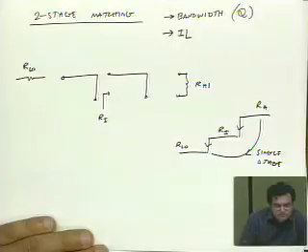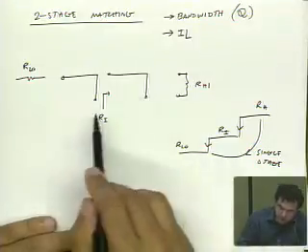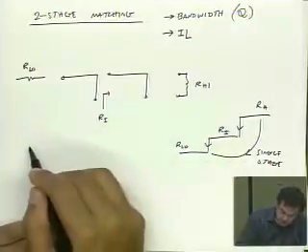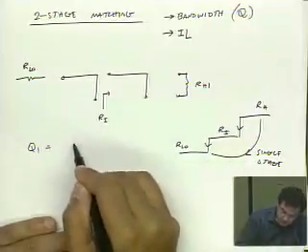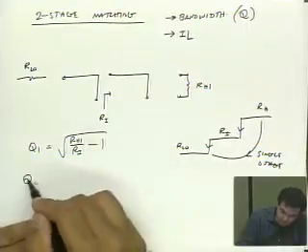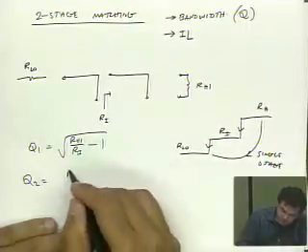Right now we don't have to amplify so much in one stage. We can split into two stages. So Q is smaller. That's right. Remember, Q is related to the ratio. So that if I were to think of this as two distinct stages, I could think of stage 1 as being R high over Ri minus 1, and Q2, Q of the second matching network, as being